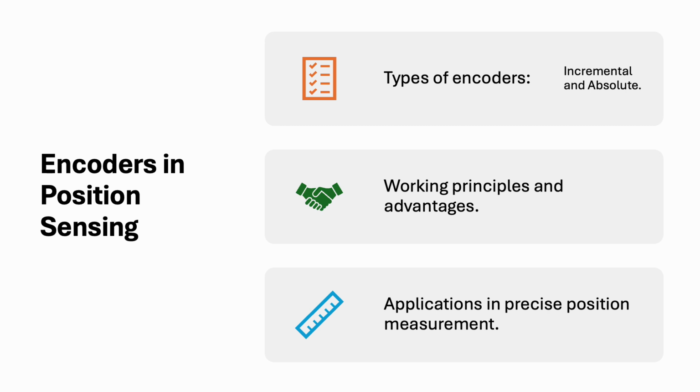Encoders are essential devices that convert mechanical motions into electronic signals, enabling precise control and monitoring of the arm's movements. The laboratory employs two primary types of encoders, incremental and absolute, as discussed earlier, each offering distinct advantages depending on the specific requirements of the task at hand.